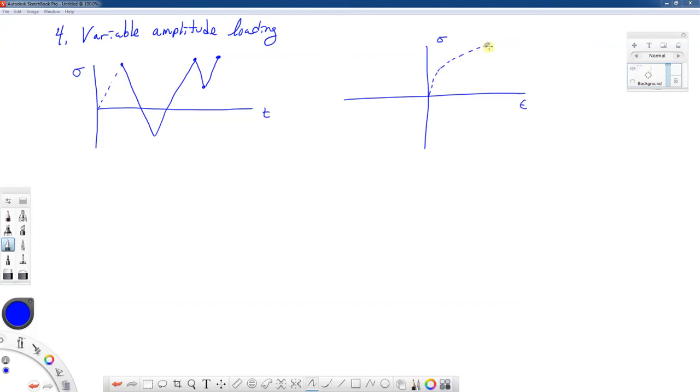All right, so I'm going to have my range, unloading with my slope of the modulus of elasticity. I have my range of 2 sigma yield, and then I yield. I'm down at the bottom point. I reload. I have a symmetric hysteresis loop. I'm back at this point, and now I have a small loop which I come down. Maybe I didn't even yield it. I'm going to show maybe just a tiny bit of yielding so we can see that loop, and then it closes back up.